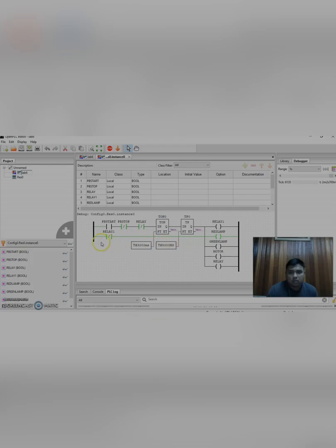So this is the initial condition, and when we push the push button start, we push through, so the counter will start to count to 3, and then the relay is on and completes the circuit. The green lamp is on and the motor is on. After 5 seconds, it will be off, and then this is continuously repeated.